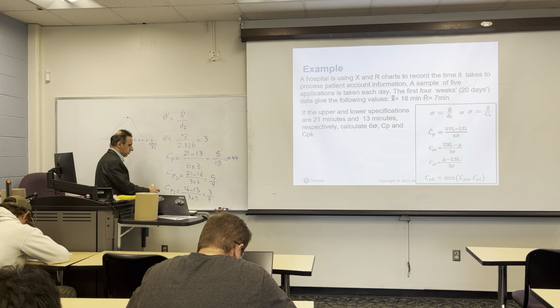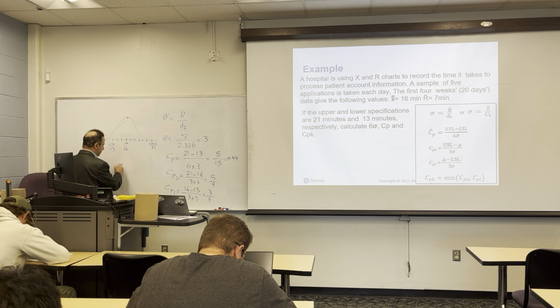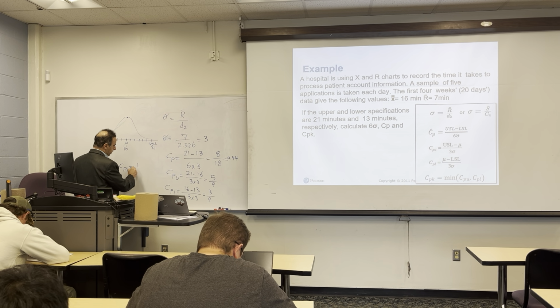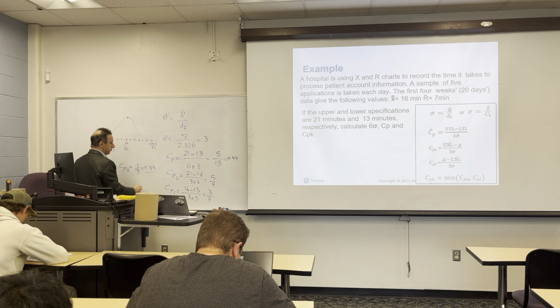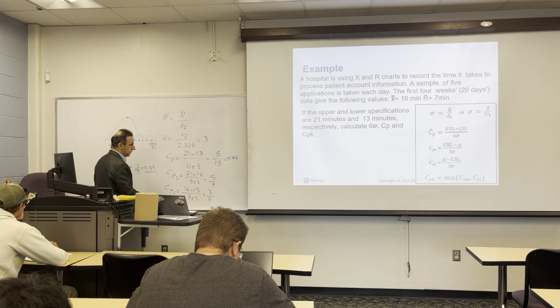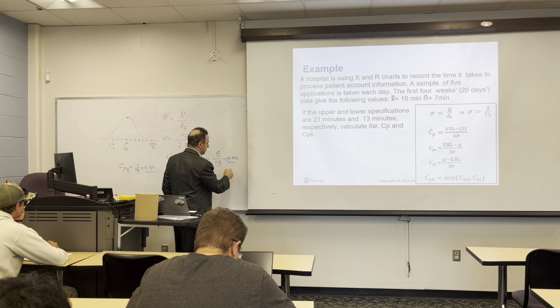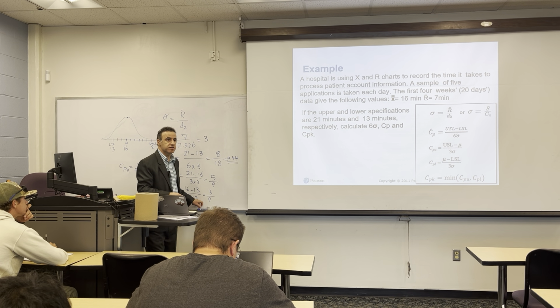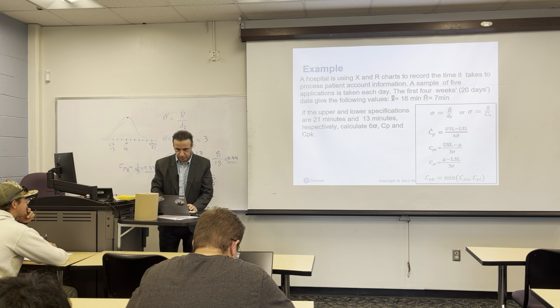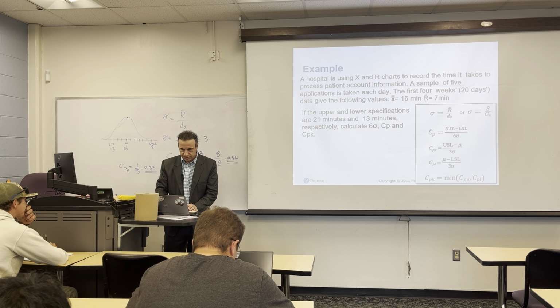So my CPL is smaller. CPK will be 1 over 3, or 0.33. So the process is not capable. Also, the process is not centered.